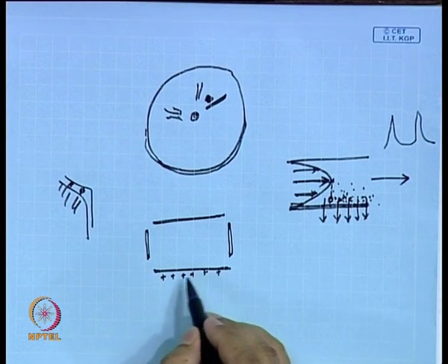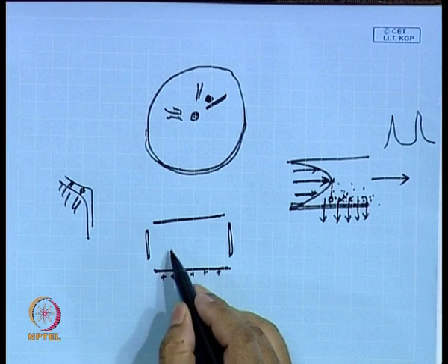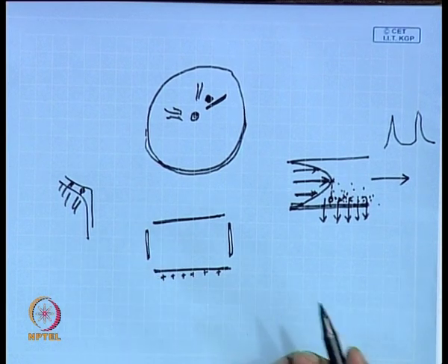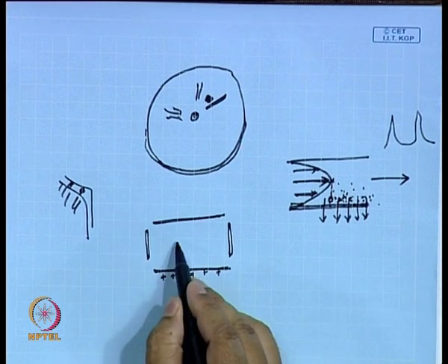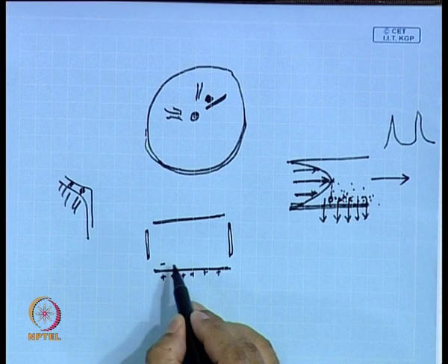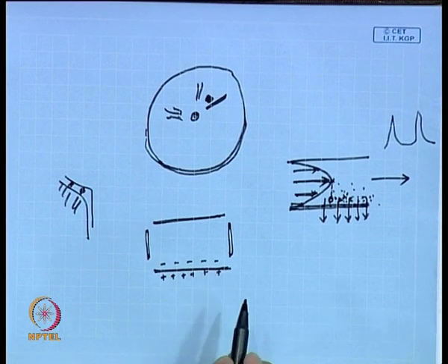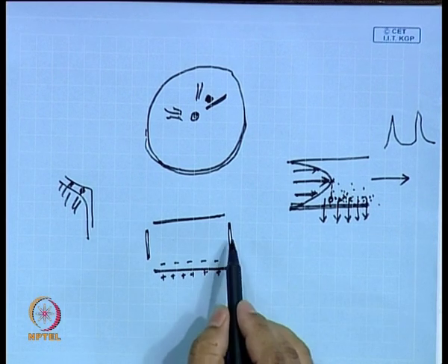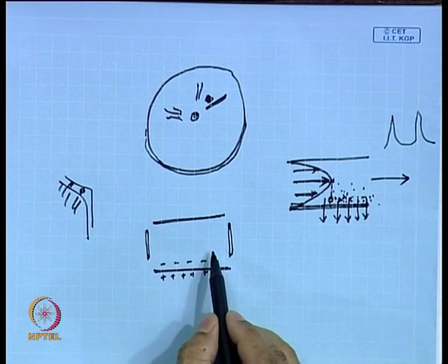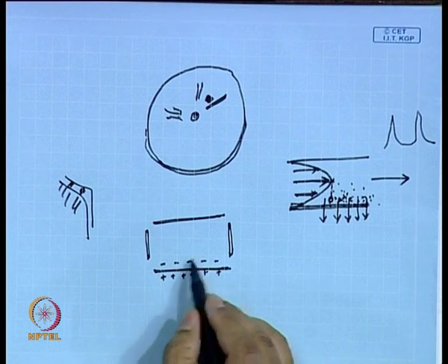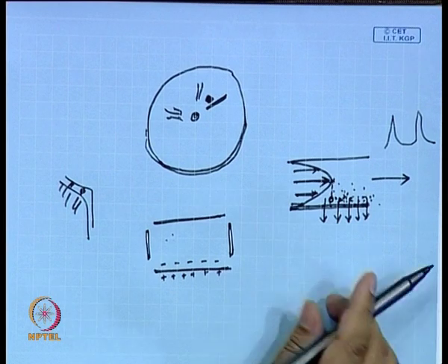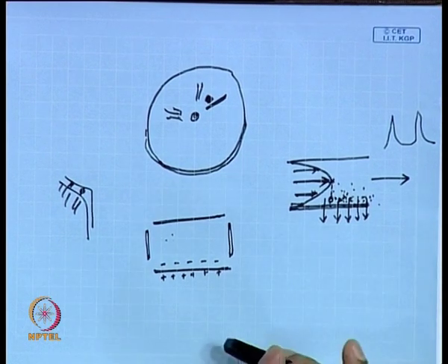If you have certain charges induced, then this polar liquid in contact with solid wall induces surface charges. So, the negative charges within the liquid will start getting accumulated on the wall, all right. And then these electrodes will be pulling these negative charges, say. While pulling them, they will pull the bulk liquid along with them. So, that is how you will generate some flow.